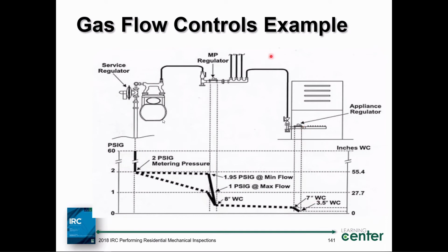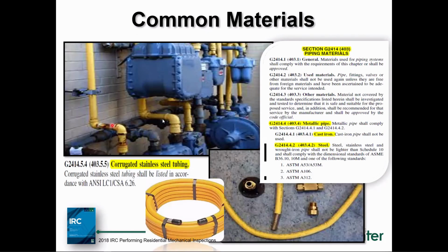I could take a pressure reading at this point, ahead of the regulator, after the regulator, just to understand what the pressure of the system is. Okay? This is called a medium pressure system up to the point of the medium pressure regulator. Okay? Now, before we start, remember the common materials? Back in this section, 2414, some common materials you remember.